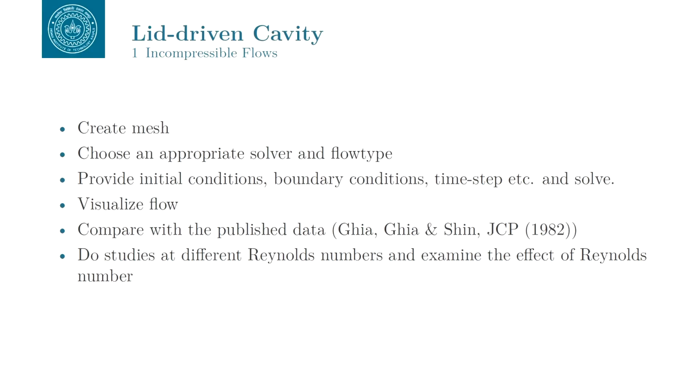If you go to Fluent, for example, you have a pressure based solver and a density based solver, although it is not necessarily a segregation between incompressible and compressible, because the pressure based solver can also be used for compressible flow problems. There you can call the energy equation and solve compressible flow problems.